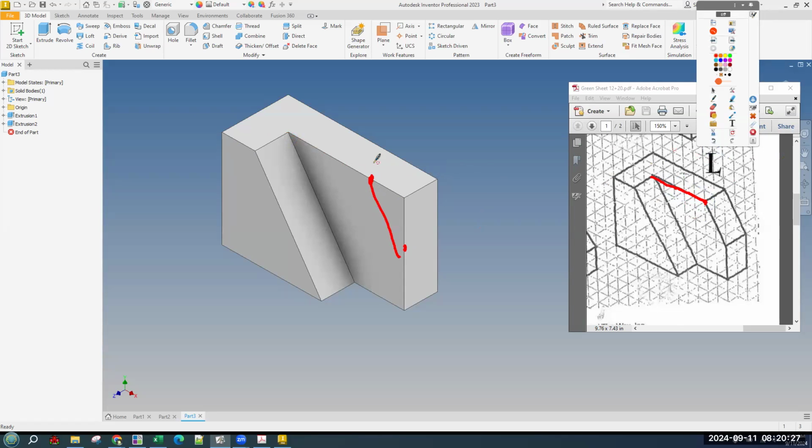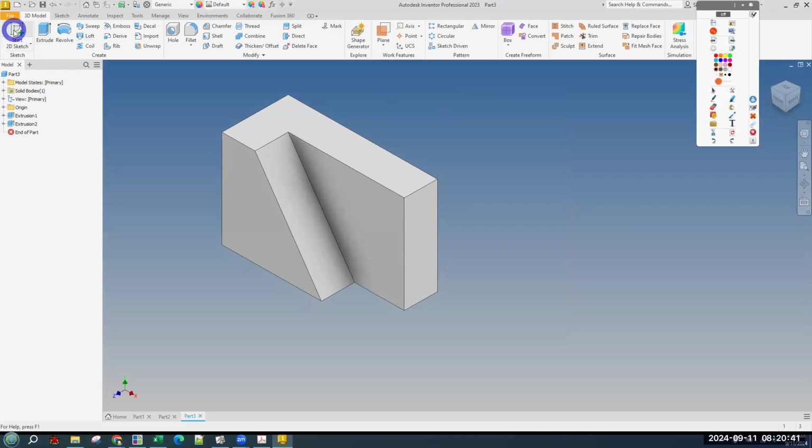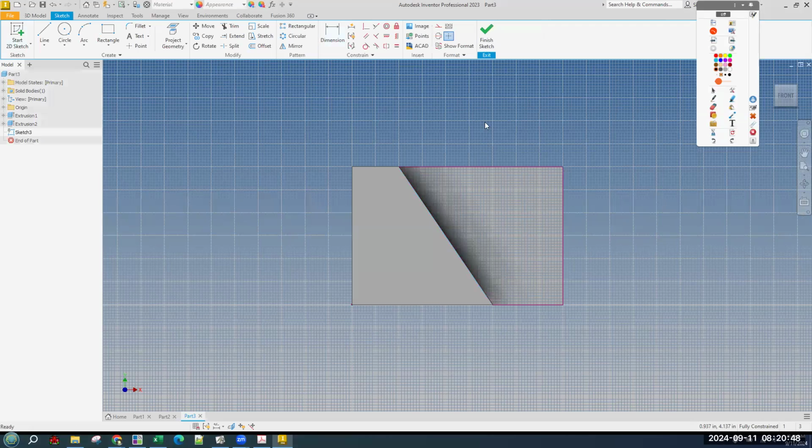And then once it's connected, cut, extrude, all of it. And I've already forgotten the numbers. Okay, the one on the right is the exact center point, and the one on the top is 5 from this corner that we will get when we sketch. So let's start a sketch. Choose the face we want to sketch on, which is this front-facing one.